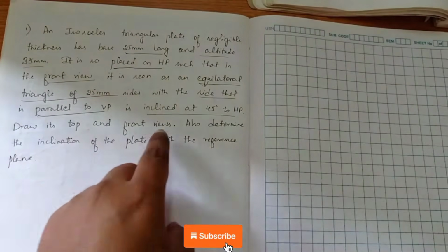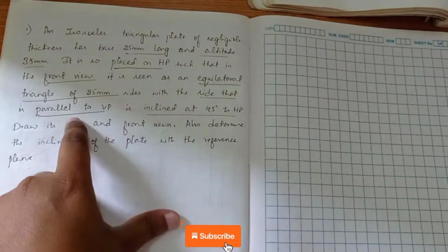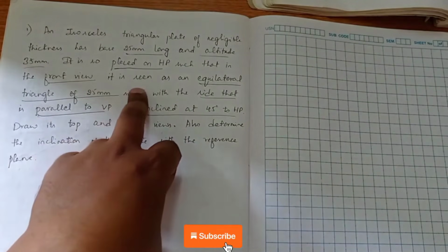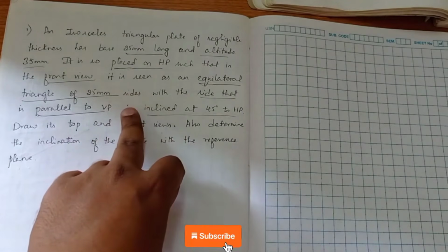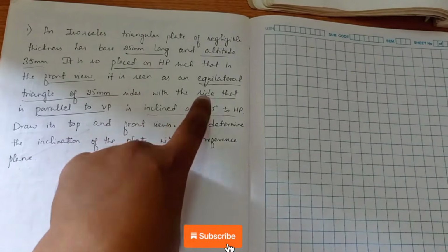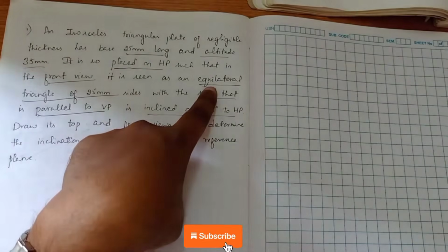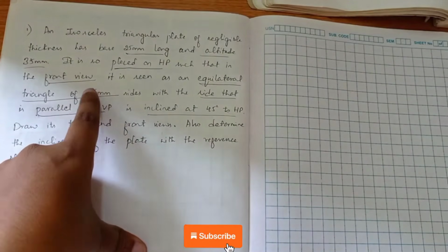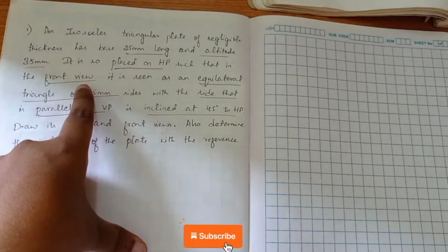Instead of that, they are telling that the side that is parallel to VP is inclined at 45 degrees to HP. So the second angle of inclination they have not mentioned. Instead, they have mentioned the second view. The second view is an equilateral triangle of dimension 25 and it is a front view. So in the front view we have to get an equilateral triangle.